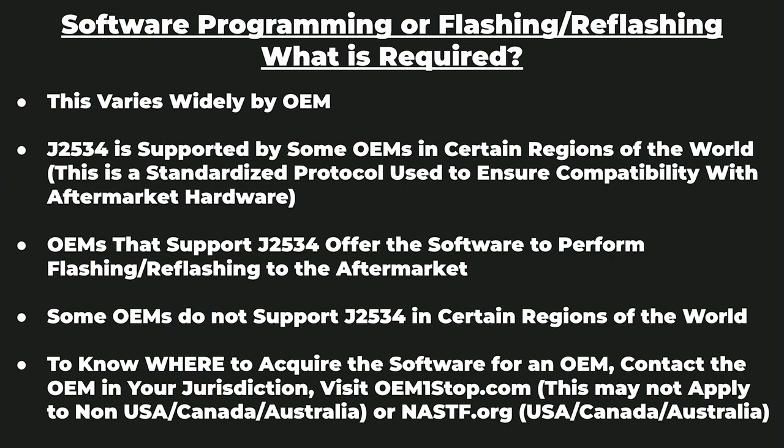And then there is programming with the factory interface, such as a Nissan VI3, a GM MDI2, a Ford VCM3. These are all factory interfaces and work exactly as the hardware the dealer has because they are the same as what the dealer has. In some countries, that is what you will have to purchase in order to accomplish programming. In some countries, you will be able to use a J2534 compliant device like the MDCI with your Phoenix Max or Phoenix Smart, or the R-Link in the future.